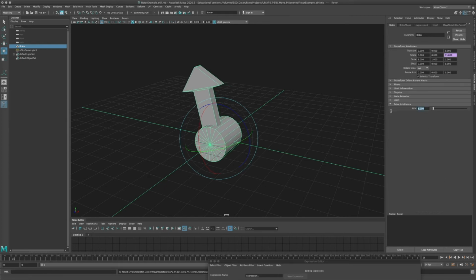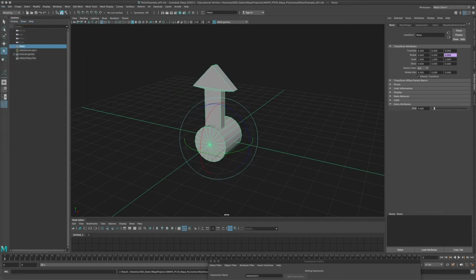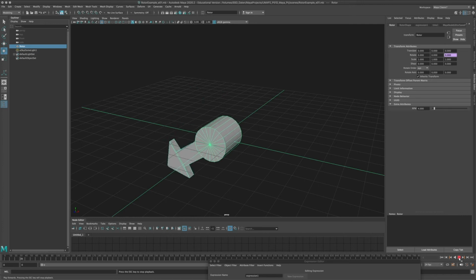To make things a little bit more obvious, let's add a rotation of 4 on every frame. So it's going to rotate 4 degrees on every frame. That's fine, and that's cool. Now I'm happy with that. That's actually a motion I want to have. If I take a look at it, that's cool. That's not a propeller anymore because nothing turns that slow in the world of airplanes, but anyway, that's the speed I want it to turn at.